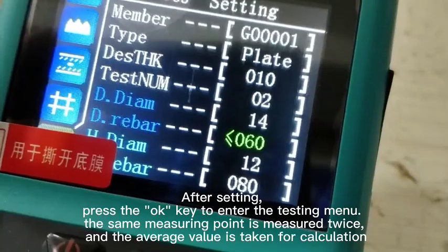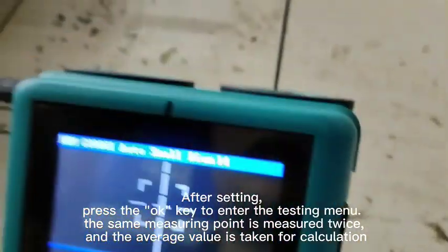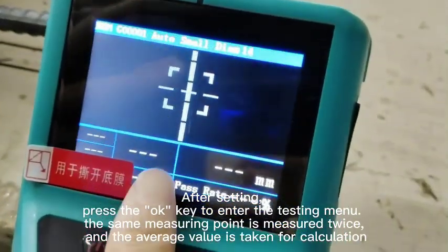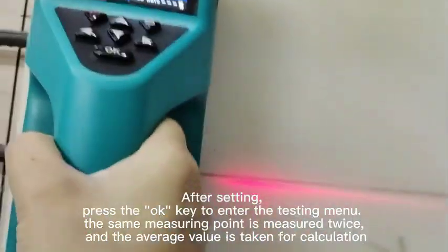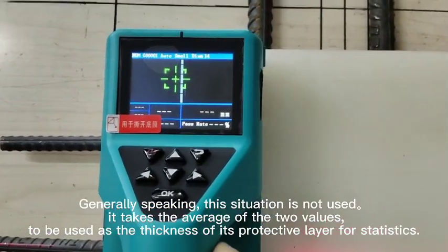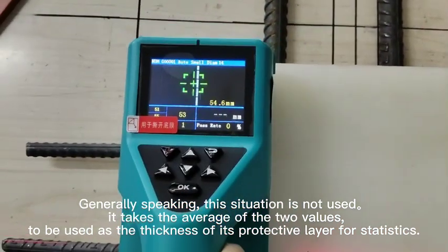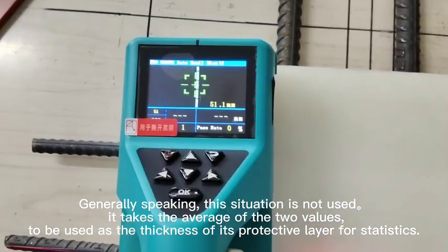After setting, press the OK key to enter the testing menu. The same measuring point is measured twice, and the average value is taken for calculation. Generally speaking, this situation is not used. It takes the average of the two values as the thickness of the protective layer for statistics.